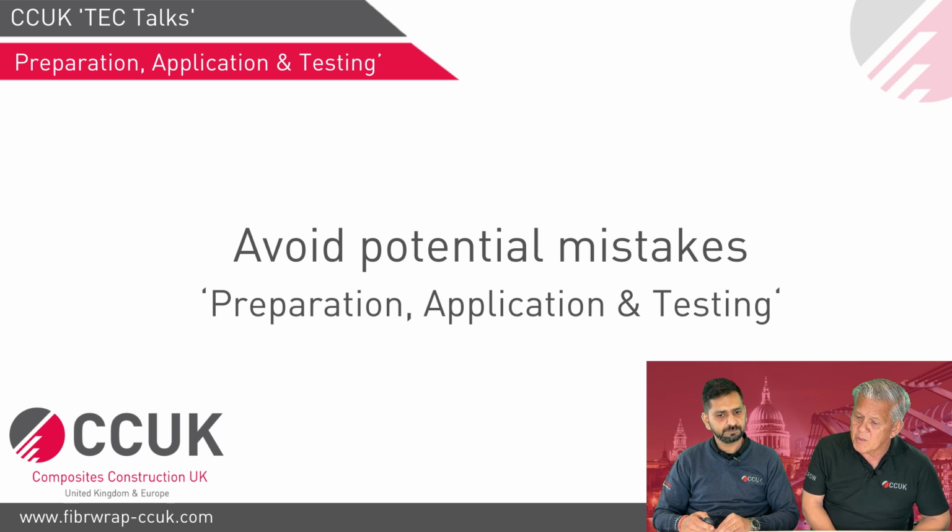So the preparation, application and testing are absolutely critical to the whole process as well. It is, yeah. FRP design is one part, and there are a few mistakes which should be avoided in the design of FRP, but even if you've designed it as well as you want, if it is not applied correctly on site, it is not going to work. So for that reason, the application is the key part in any FRP strengthening scheme, and for that reason, we do not subcontract it at all.